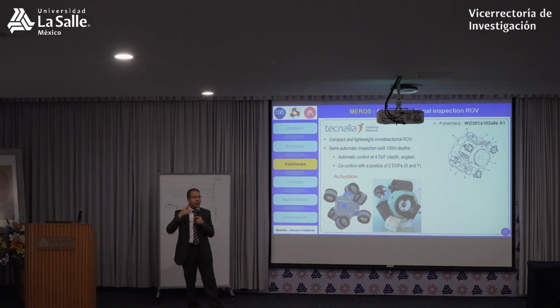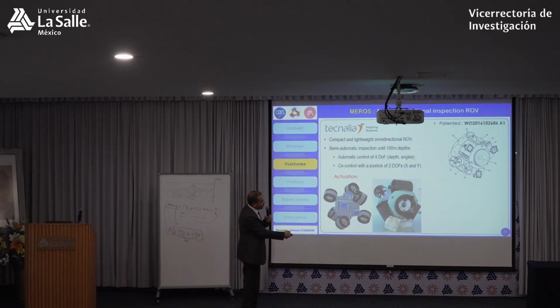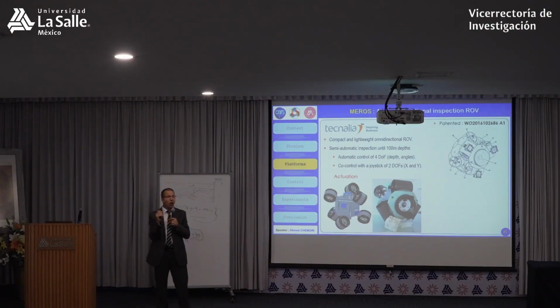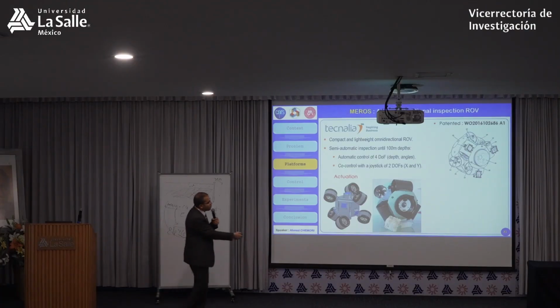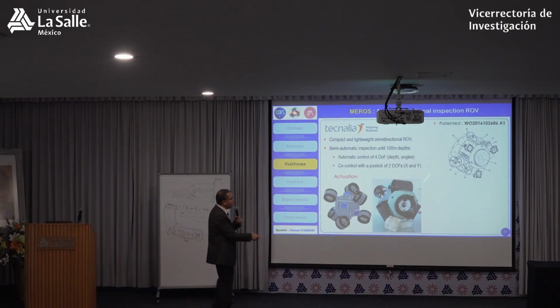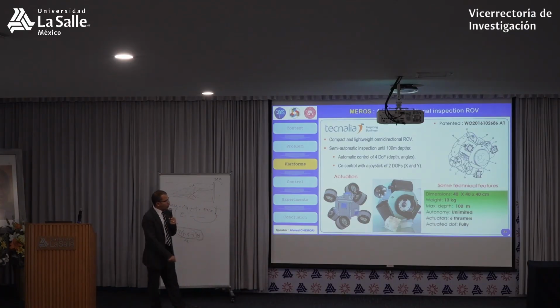We have 3 planes, and for all of them, the orientation of the planes of each 2 propellers has been computed based on optimization, such that we optimize the control efforts that push the robot in the different directions. This is to obtain an omnidirectional underwater vehicle. It means that wherever the vehicle is, whatever the direction you want to go, it's possible. And we distribute the forces that push the vehicle in all the directions the same. So it's a very good solution.